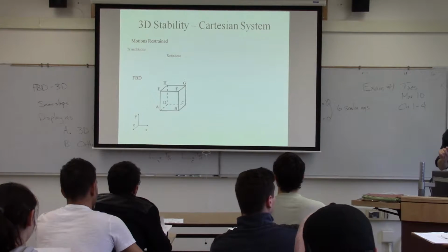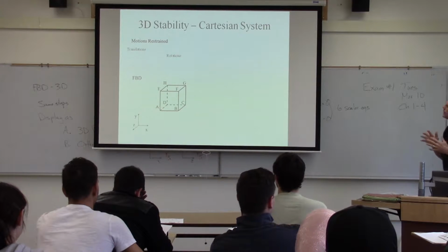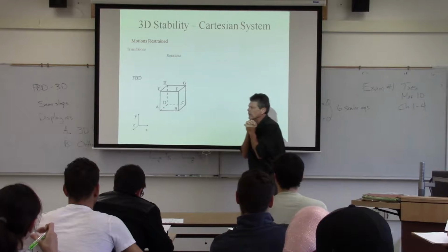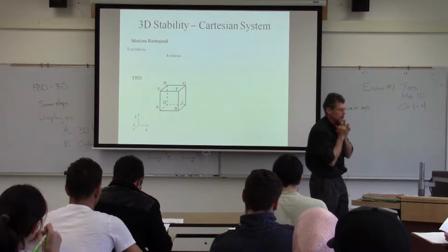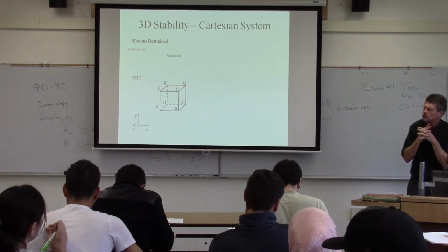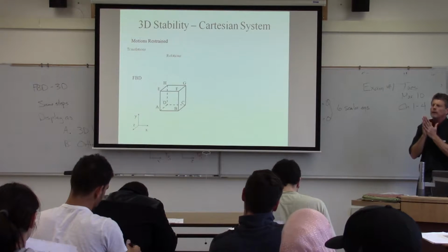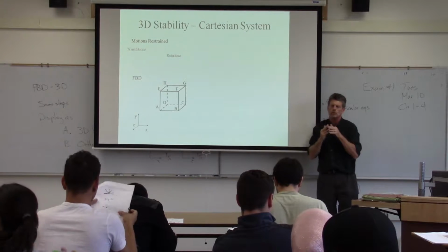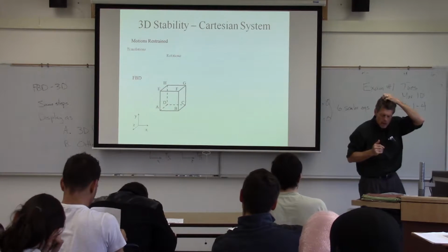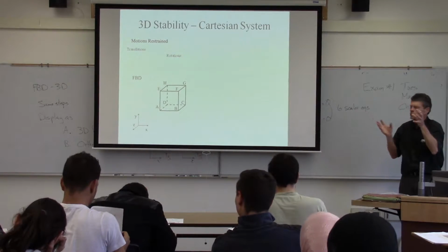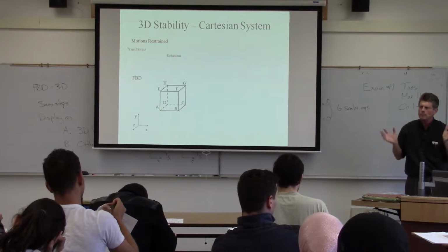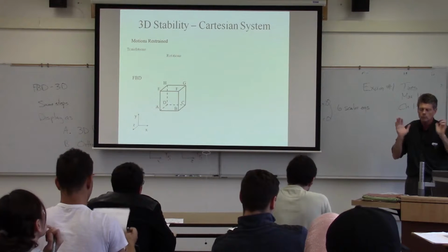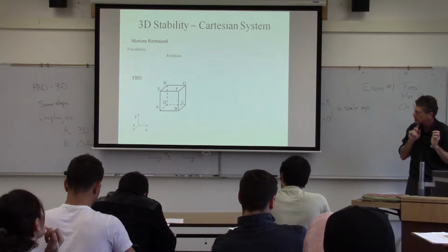Okay, next part we'll talk about is stability. We don't talk about this too much in statics, but it's a good idea just to get an understanding. What I'm going to be doing is going through sets of forces here and explaining how they work. So when you start thinking about structures, you want to think about whether your support cases are going to be able to provide resistance against all these potential motions it might have.